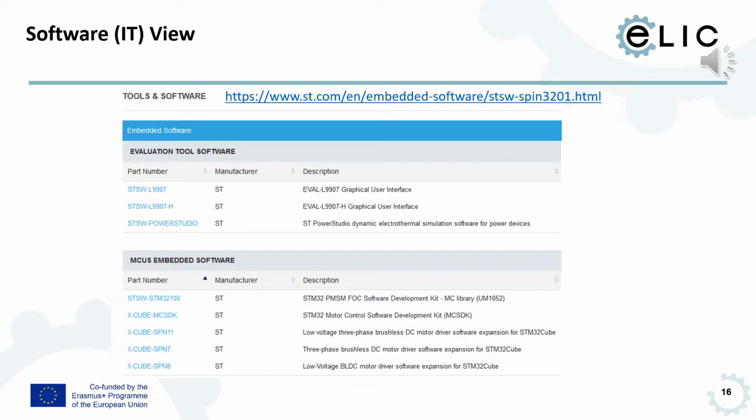Here you also find a link to ready-to-use software if you want to program an FOC controller for an e-motor. There are development kits. This is only one example of these development kits. They are specific to the inverter and controller boards which you are buying, but usually you get this development kit when you buy them, like here the STM32 PMSM FOC software development kit, and you get also the graphical user interface.